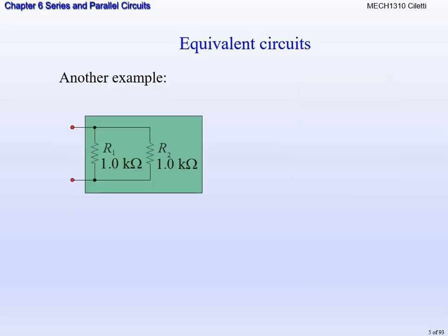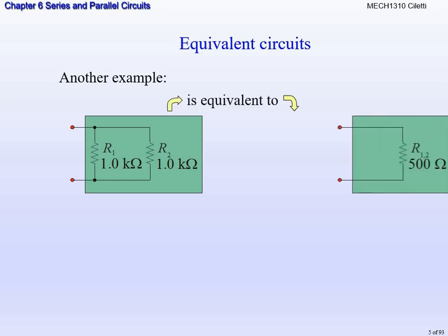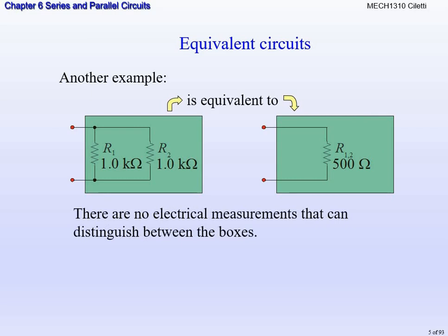So what do we have here? We have two parallel circuits now. We remember these from chapter 5. We can combine these and make an equivalent circuit. Since it's two 1K resistors, you should remember the total parallel resistance has to be less than 1,000 ohms. It has to be smaller than the smallest resistor. But we can make it so that it's what? 500 ohms.